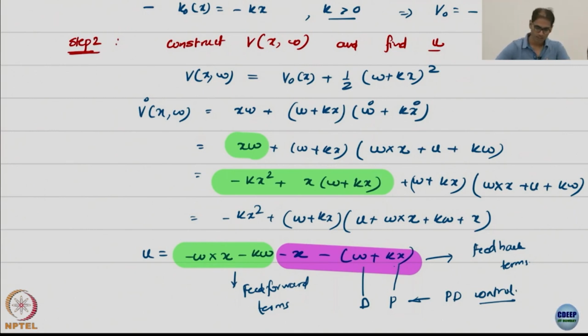In the linear domain these terms will have relatively smallish contributions. And the integrator is what creates this internal model. So it adjusts the steady state error. So the I is essentially a replacement for these terms. When you don't know these terms too well, you would employ an I term. That's the principle of why PID will work relatively well.